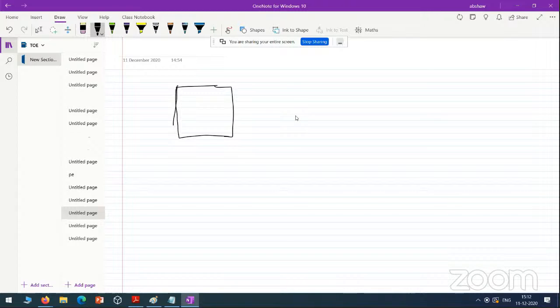Now, how do we write this gamma xy? For the two-dimensional case, gamma xy is del u del y plus del v del x. Then epsilon xy is written as half of gamma xy. This is half of del u del y plus del v del x. So gamma xy and epsilon xy are two different representations.